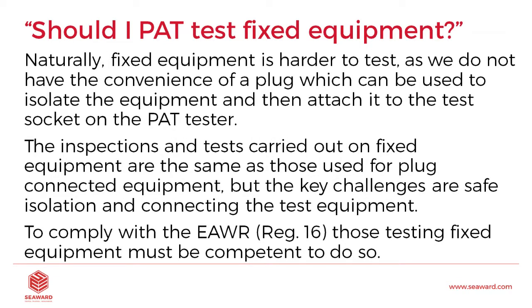Naturally, fixed equipment is harder to test, as we do not have the convenience of a plug, which can be used to isolate the equipment and then attach it to the test socket on the PAT tester. The inspection and tests carried out on fixed equipment are the same as those used for plug connected equipment, but the key challenges here are the safe isolation procedures and actually connecting the test equipment to the fixed appliance itself. Again, need to point out here, to comply with the Electricity at Work Regulations, Regulation 16, those testing fixed equipment must be competent to do so.